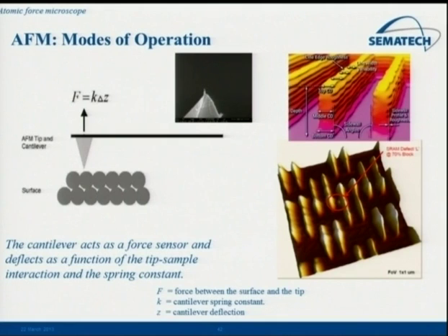So in theory, you can pull out a lot of this information, but the problem is these probe sizes are typically 20 to 30 nanometers, and therefore, as you get down to 20 or 30 nanometer dimensions, it can be very difficult to measure in between the lines. So the reality is probably this edge is measured fairly accurately, and this one in between is probably not measured fairly accurately. So that's why this is typically used a lot in process development to figure out what's going on in your process, but less often used in manufacturing.